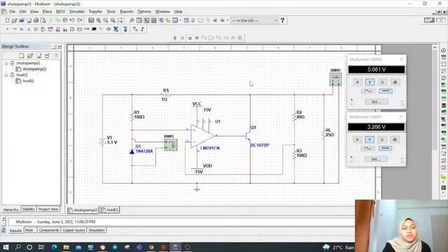After we get all the parameters, we construct the circuit. So this is my circuit for the voltage regulator. We put the multimeter at the load because we want to measure V naught, and we try to run it. So for the voltage output, we get 5.061, which is nearly 5 volt. And the voltage across the Zener diode is 3.266 volt for the simulation.